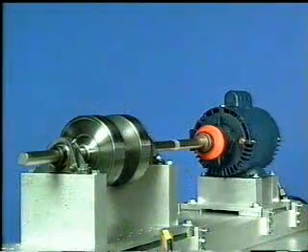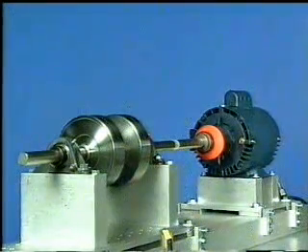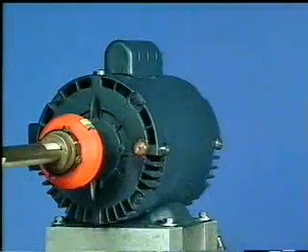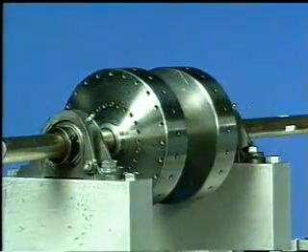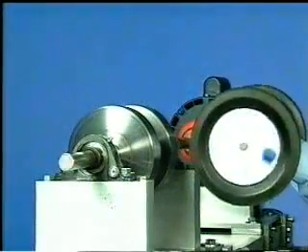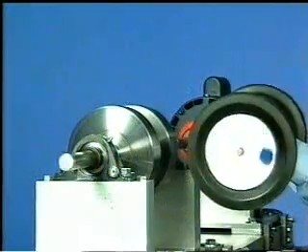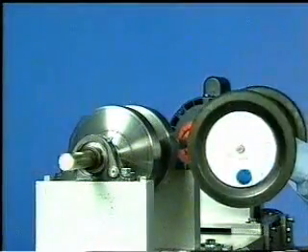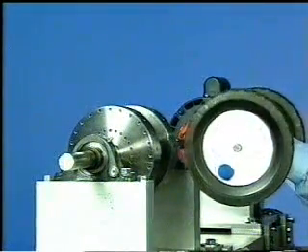When diagnosing an unbalanced condition in a machine, we are usually referring to the unbalance of a component. That is, either the driver, such as a motor, or the driven unit, such as a pump, fan, and so forth. Like the unbalanced wheels that pull on the shaft, unbalance in the machine component pulls the shaft, generating a bump each time the shaft turns. This type of unbalance produces movement in the same direction along the shaft.